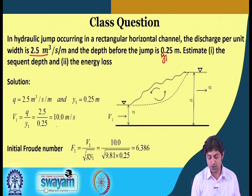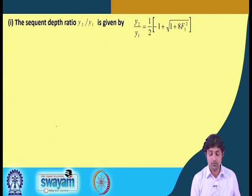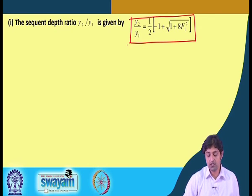So, we know the Froude number at location 1, and we know y1. So, we will be easily able to find y2 by y1, by the formula y2 by y1 is equal to half into minus 1 plus under root 1 plus 8 F1 square.